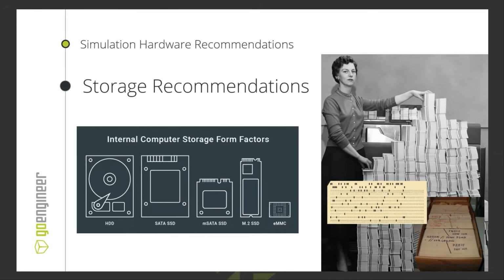The amount of RAM you need depends on the total degrees of freedom that you have for a finite element problem, and it also depends on the solver that you're using. In general, the FFEPlus solver needs about 1 gigabyte of RAM per roughly 2 million degrees of freedom, whereas the Sparse solver needs about 1 gigabyte of RAM per roughly 200,000 degrees of freedom.